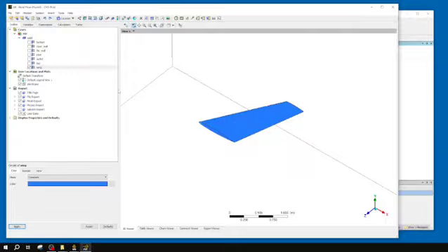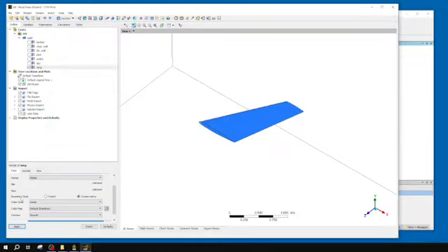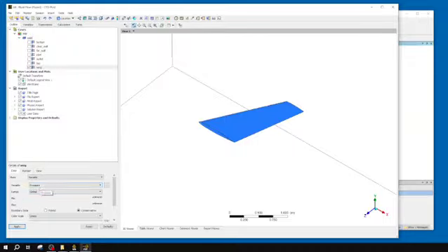Right now, we've only been looking at constant colors. Good for, I don't know, defining your outlet and inlet. But not great if I want to show a variable. And I can show a variable. So if instead of a constant, I just clicked on constant, I can move down to a variable, and now I can display a couple different things. I have a bunch of what they assume are common things to display if I just click on pressure. Or I can see the entire list by pressing these 3 dots.